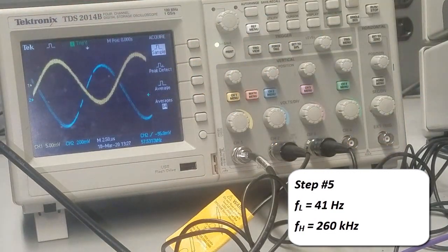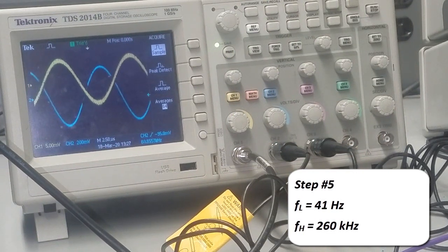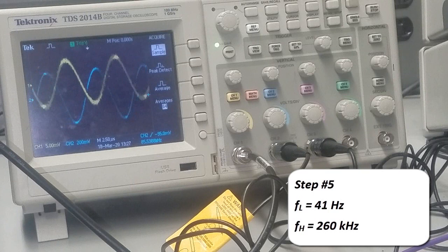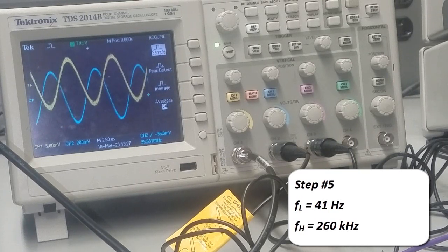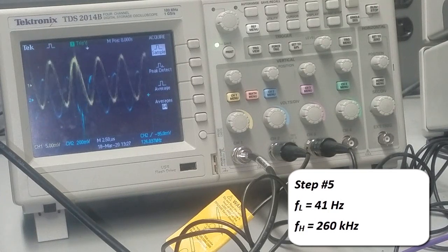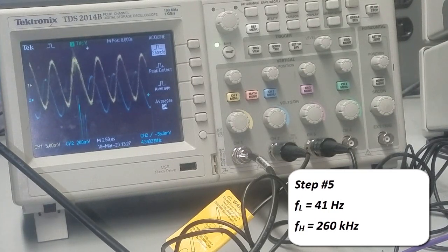It's slowly dropping, but you know, that's at 67 kilohertz. So the higher cutoff frequency was found to be around 260 kilohertz. So now I'm at 73. I'm going to move by tens. That's like 95, 105 kilohertz, and so forth. I'm increasing the frequency. You start to see that the gain starts to drop, and I start to get some noise here, right? You can see in this area there is some noise.